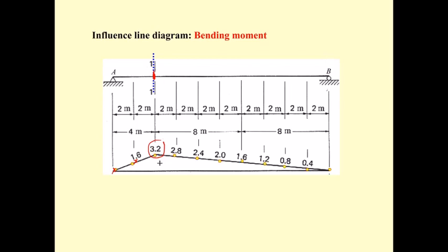Okay, to get this. And this time the influence line of the bending moment is positive. So the loading pattern is like this. Now you can see that the loading pattern can change with the change of influence line diagram, such as the loading pattern for this bending moment and the loading pattern for the shear force at the same section 1-1. They are different.